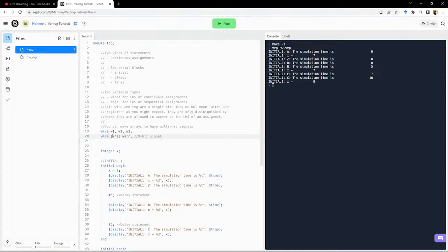Now, how do you understand this? This is another strange quirk of Verilog, and I don't know why they did this, okay? When you define an array, you give its lowest valid index that you're allowed to index into, and its highest index.